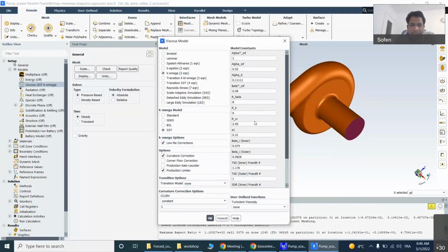These are the coefficients. Once you derive the governing equation for the k-omega model, you will find a lot of closure coefficients need to be modeled, because you will get third-order pressure-strain velocity correlations, etc., for which you don't have any closure at the RANS level. So you have to model it, meaning you have to assume it in terms of some gradient of the quantity: simple gradient diffusion, hybrid gradient diffusion, or the generalized gradient diffusion concept.